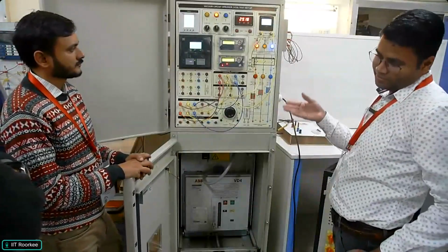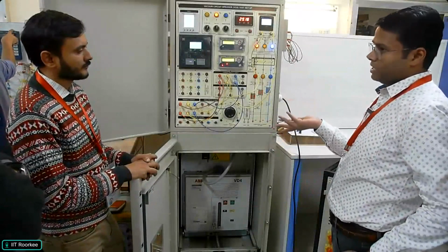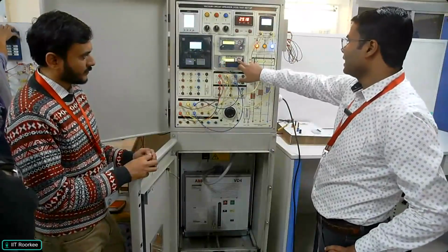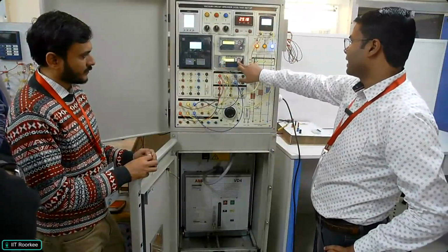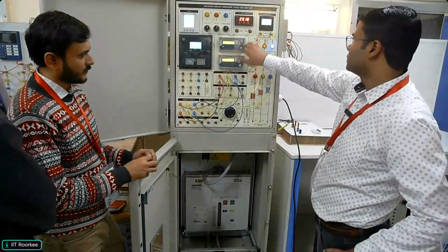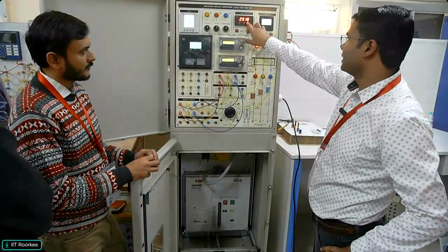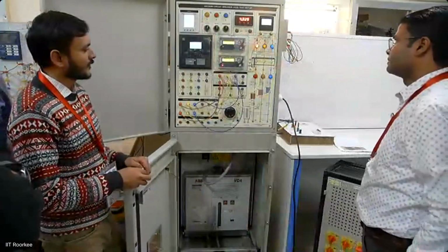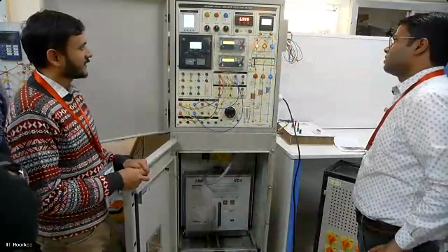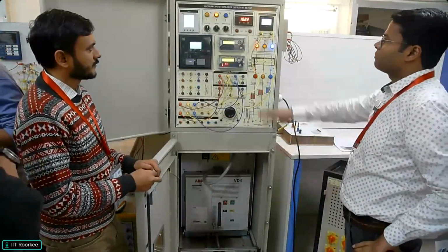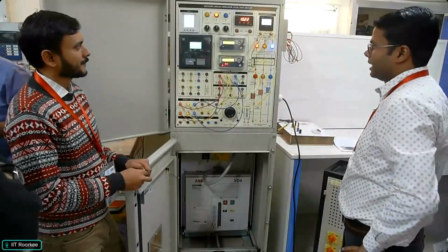When we go for 5, 6 ampere or maybe 10 ampere or more, then maybe the characteristic will be different. One more thing we can do is the definite minimum time. Let's see how much time it will take. As we said already, the definite minimum time is 10 seconds. It has taken 10.22 seconds, and that 0.22 second is the human error.